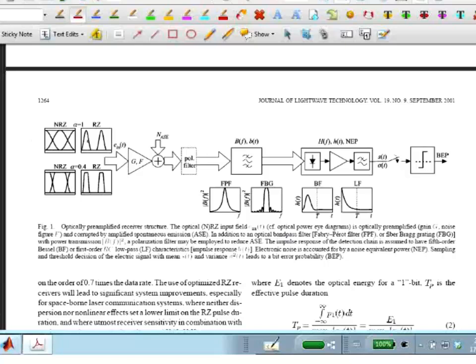They're generating different pulse shapes. Here, they're doing what I think is called a cosine squared, and this is what they call a practical NRZ. Even the equipment cannot produce a perfect rectangular pulse; there are rise times involved in the equipment, so this is using a reasonable pulse shape. So they're doing pulse shaping before they transmit.